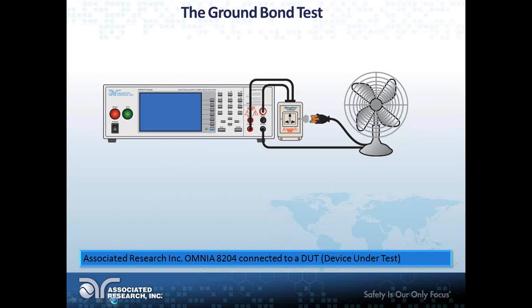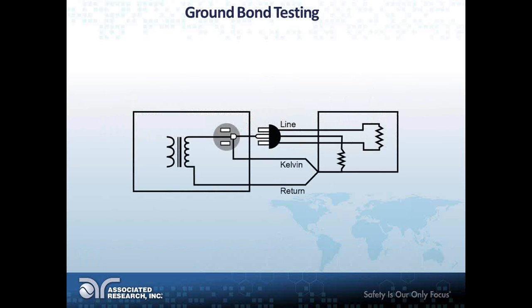of the instrument. So electrically, what we have going on is this. On the left-hand side there, you can see our current transformer. You can see the current is injected onto the cord, which is right in the middle there. You see where it says line. That represents a 3-prong cord, and that goes out to the DUT, which you can see represented as a resistance on the right-hand side, just a little box with some resistors in there.